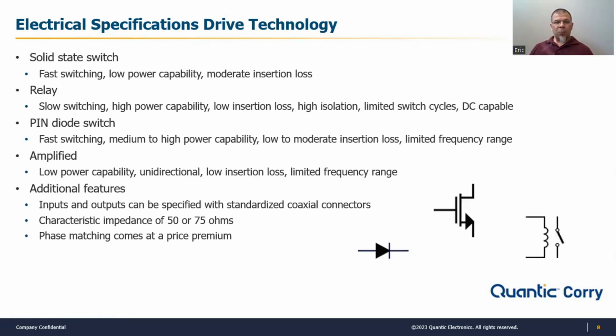So we have a number of technologies that will fit the bill, if you will. We've got solid state switching, or what we call FET-based, MOSFET-based switching. We've got relays, electromechanical relays, excuse me, and pin diode switches.